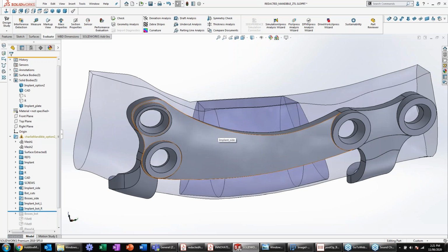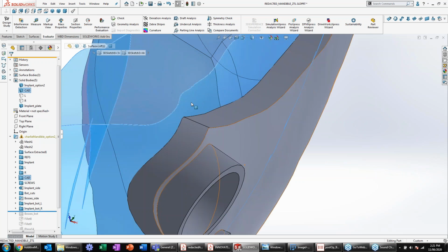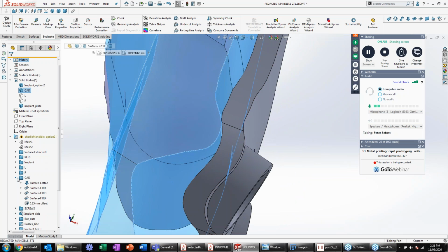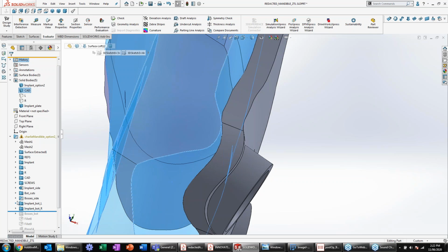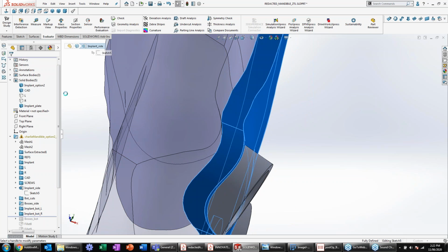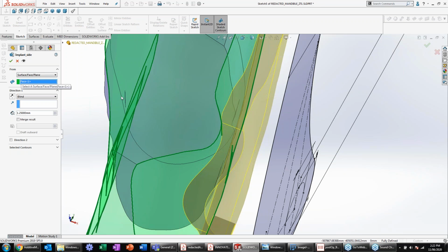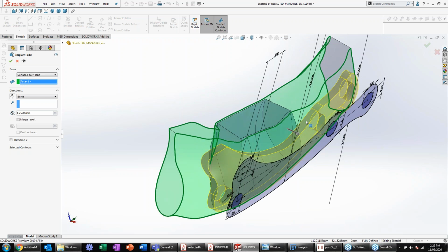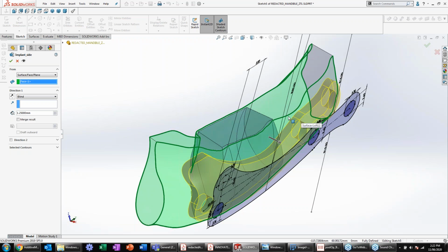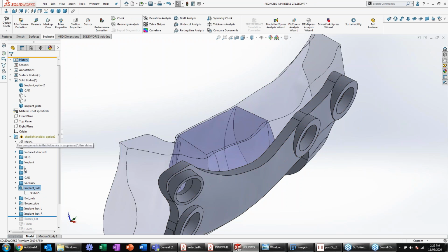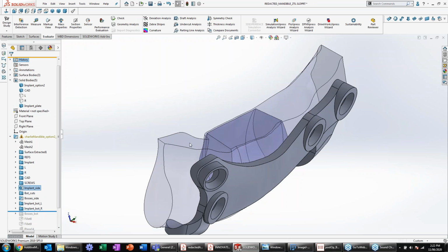Then what we can do is from that surface we created, from the scan to 3D functionality, as it extrudes right from that surface. So when you're extruding something, you've actually got an option to extrude from a surface, and that is right up here at the top of your extrude from, and we chose the surface that we had got from the 3D scan data. So that's the trick to making it conformal. And then from there, it was essentially your normal parametric design, but with a few tricks to get references in the right place.